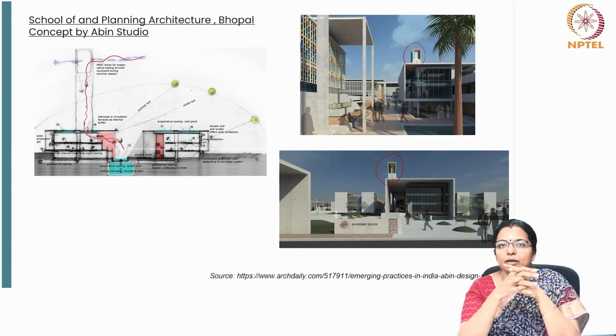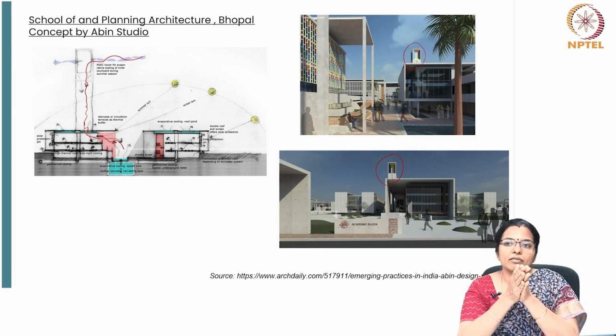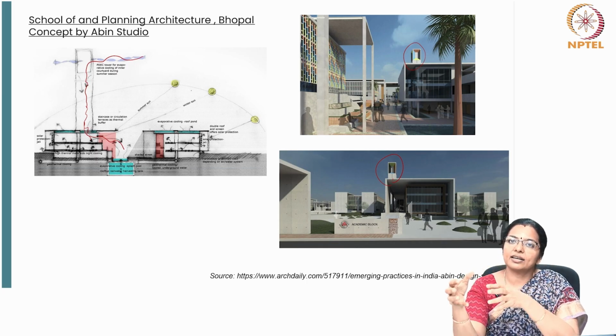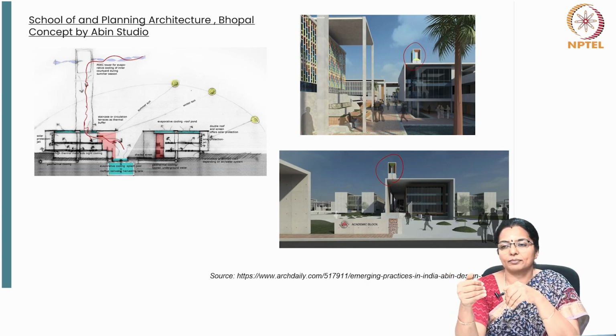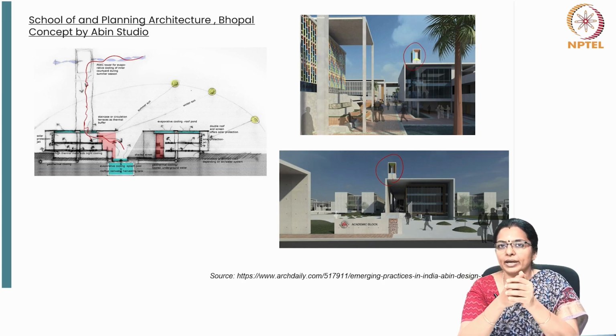So, in today's class, a very simple technique, direct evaporative cooling. We also saw the various forms in which this concept can get translated in architecture to cool indoor air. This technique is primarily suitable for hot and dry climate and is not really suitable for humid climate.